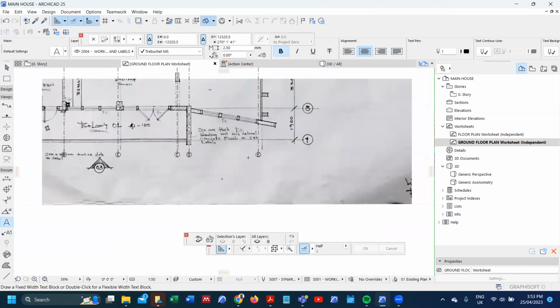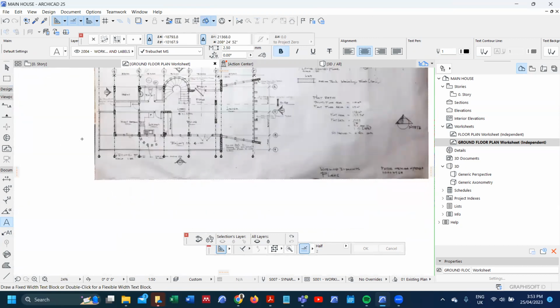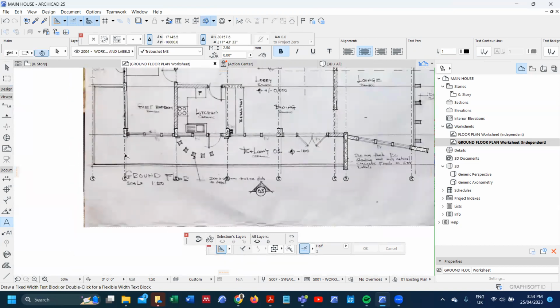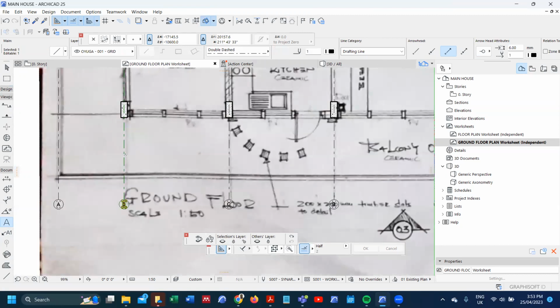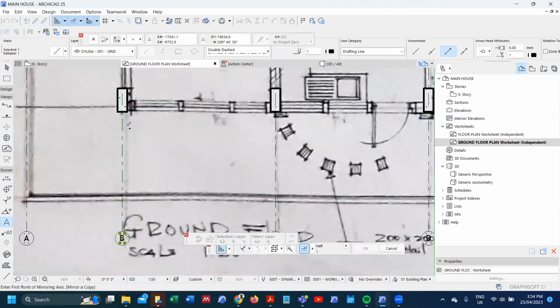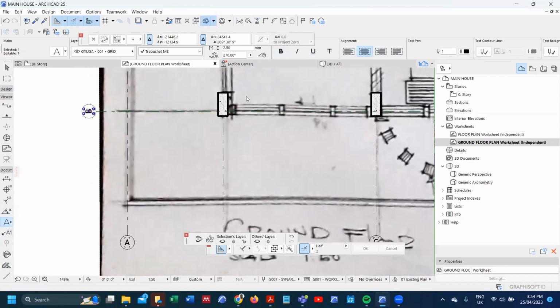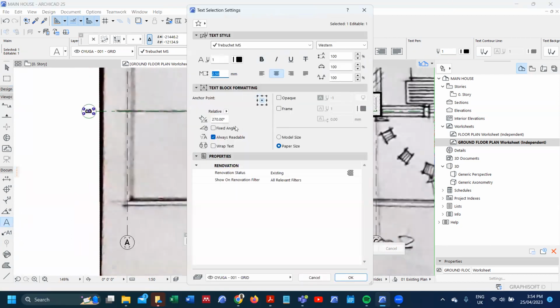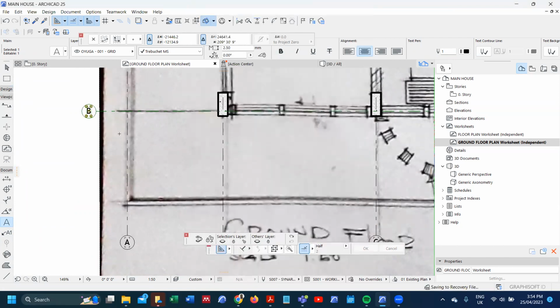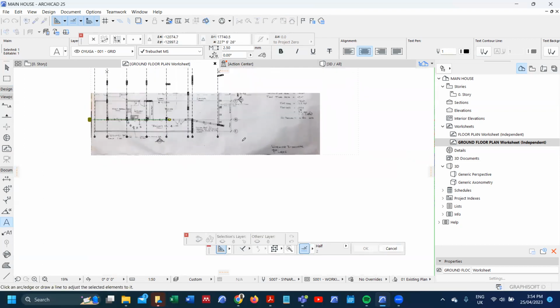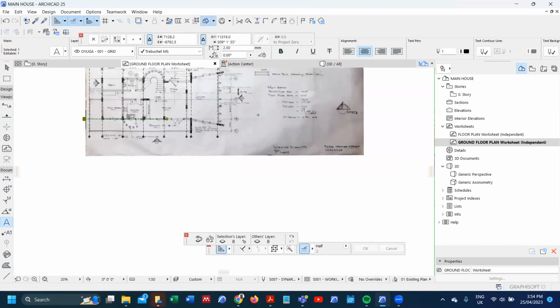Okay. So we have already placed those grids. So allow me to create a grid, the horizontal one. That one I can do by just mirroring a copy of one. Allow me to mirror a copy of that. While mirroring it, ensure that the text orientation is 0, so that it's legible, and ensure that the grid line goes beyond